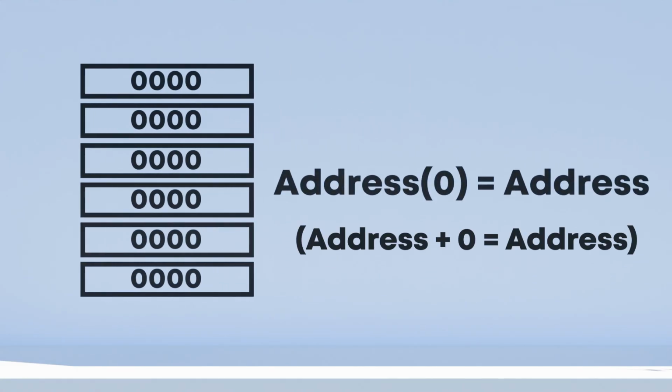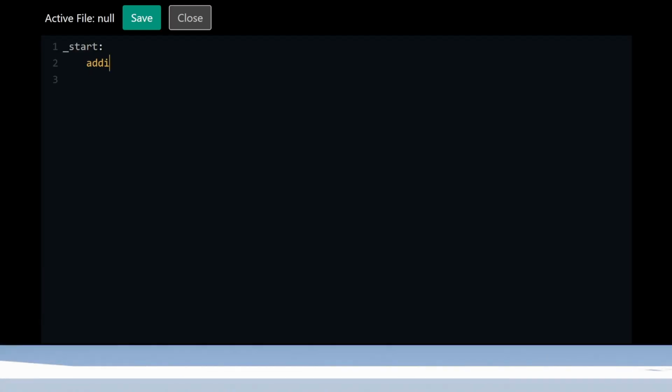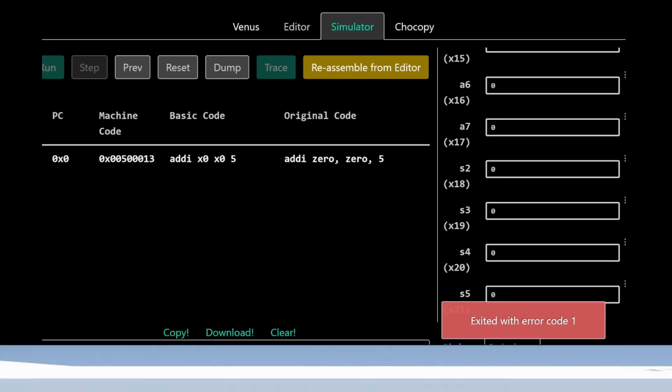It would be simpler if we just used a register with a value set to 0. Then you could just write the actual address we want to store or load something at here, and not have to worry about an offset. But lucky for us, that does exist. The first register, in fact, is called a 0 register. The amazing property is that its value is always 0. Even if you try to change it, it won't work.